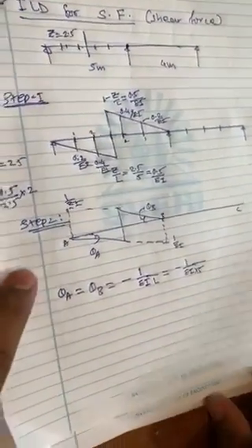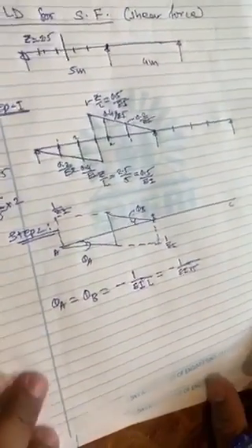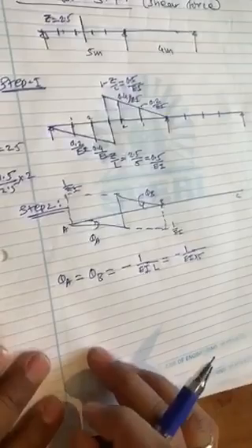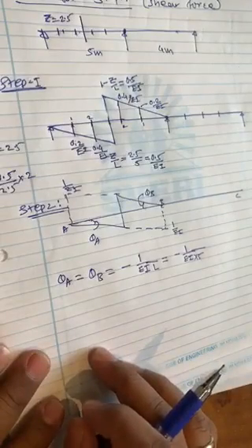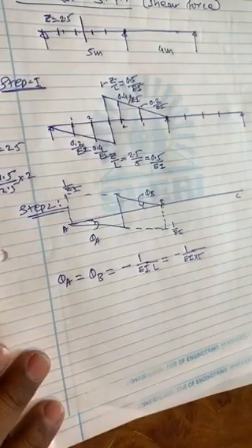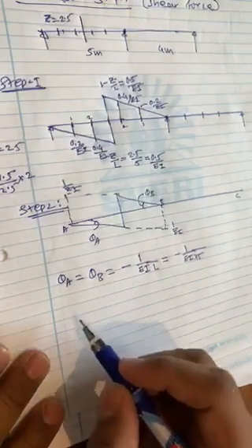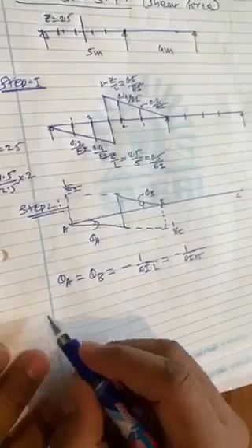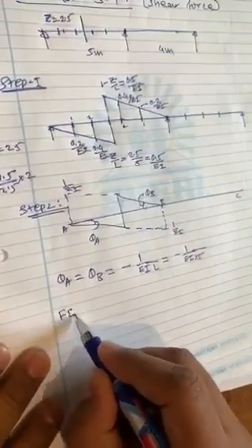And then similar to our stiffness method end movement formula, we can apply the stiffness method formula. So that is FEM plus 2 EI by L in bracket 2 theta A plus theta B. In this case, FEM is not there, so directly we are starting.